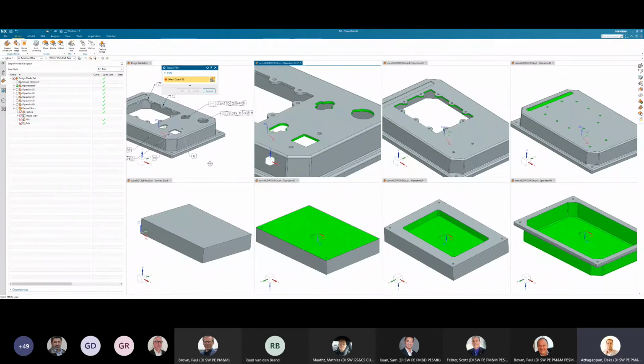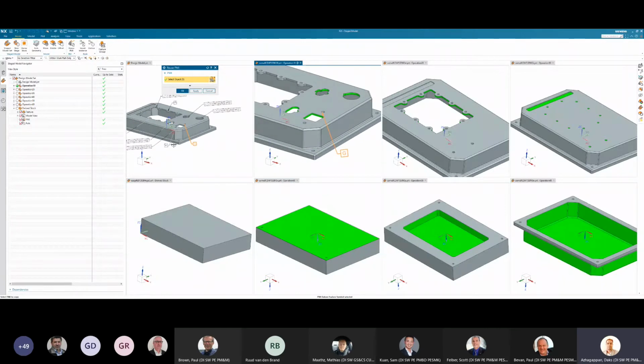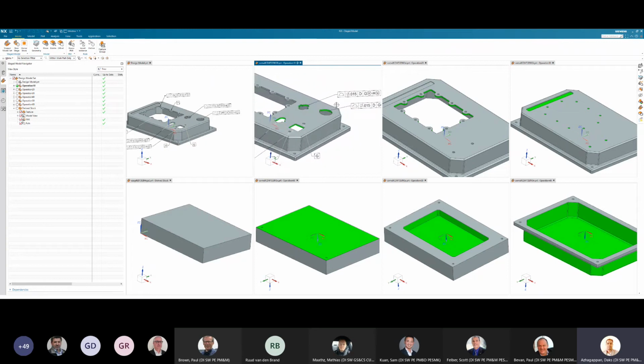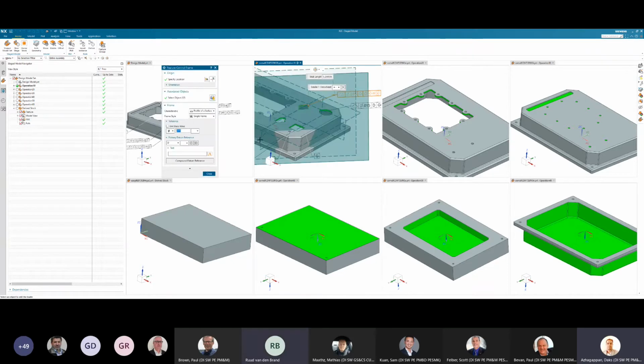I need the datum G and H. I can immediately select this one. So it gets populated. You can see here I need the H. I also need those other feature FCS informations. When I accept this one, you can see here it is copied into the operation I'm working on. It is also actual PMI information. When I double click on it, you will be given all that information. So typical PMI edit function you can see here, right?